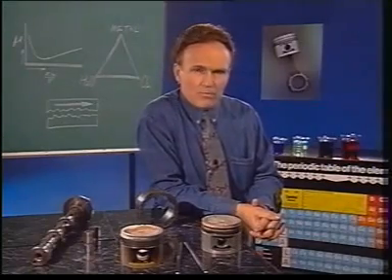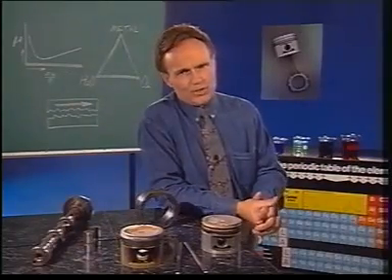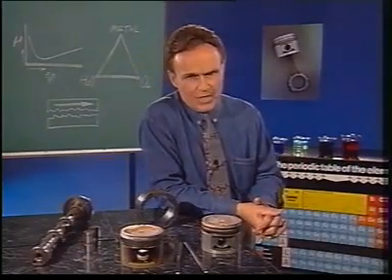These additives form a protectant film of low shear strength, but with a high solid to liquid transition temperature on the meshing surfaces. This film, rather than a continuous oil film, reacts with and coats the microscopic peaks on the surfaces of the components, protecting them from friction and excessive wear.